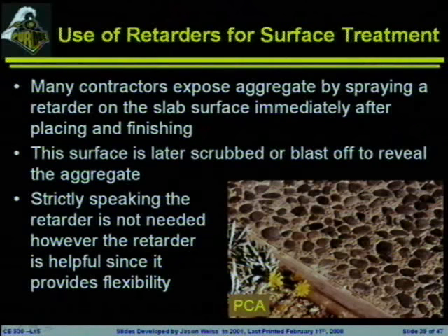One of the other types of applications where these are starting to become more and more popular is the use of retarders for surface treatments. Here in the bottom corner you can see an exposed aggregate type treatment. The idea here is that the admixture would not be integrally mixed. What you would have is the concrete would be placed and then you would come by with sort of a sugar solution to spray on the surface. What this would do is it would keep the top surface from hardening, and then you could come back later on after the rest of the concrete is hardened and spray off the top surface of the paste.